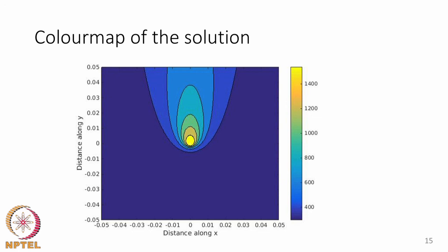Now, you can see that ahead of the weld pool you have the contours coming very close. The distance between each pair of contours will give you an idea on the temperature gradient that is located there. And as the heat source is moving in this situation vertically downwards, then you can see that there is a trailing of the heat behind the torch.